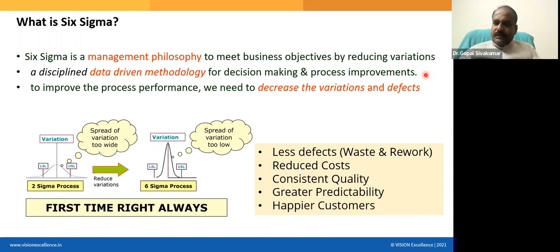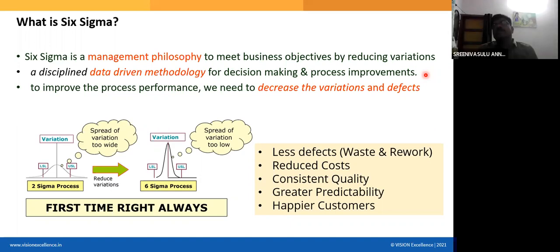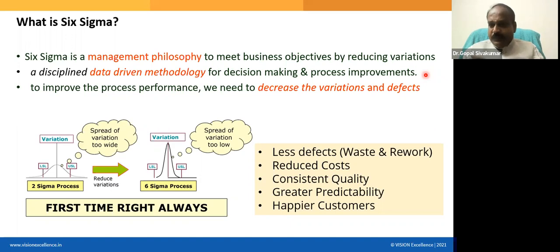Tell me what will happen if the hose internal diameter is more than 10.2. Let us say it is 11 mm now. Now what will be the problem you will face? It's going to leak. There will be leakage because the fitment will be loose.